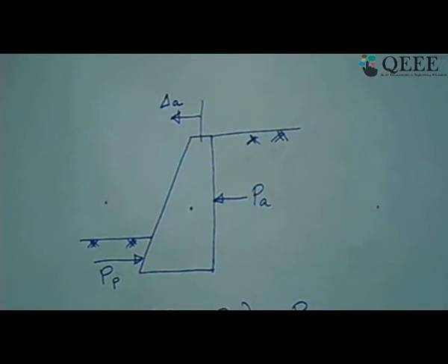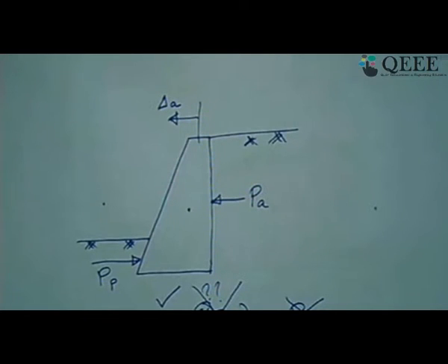That is the reason if you deduct the full passive pressure, you will be grossly making a mistake in your calculation of pressure. So it should be some fraction or some percentage of the total passive pressure which you need to deduct. And how much that percentage is, is not known completely. So in many cases in design, people don't use this deduction of passive earth pressure at all. We only design for the active state of earth pressure for the wall, not for the resultant pressure.